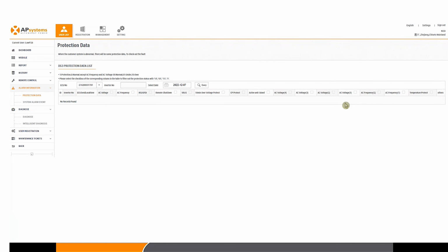Now, however, I know that when you try to use cross mix of panels, inverters on the same ECU, there has been some issues because you need to make sure that the ECU is updated to the latest firmware when you try to mix 2 inverters together, because some firmwares are more designed for YC600s and some are more designed for QS1s or DS3s, but we've made sure that the newest firmwares we have will be compatible for everything in the same unit, basically. Okay.